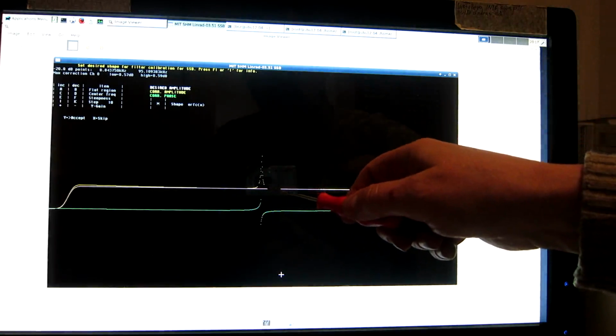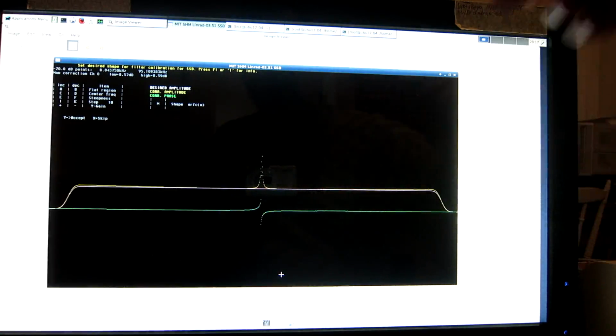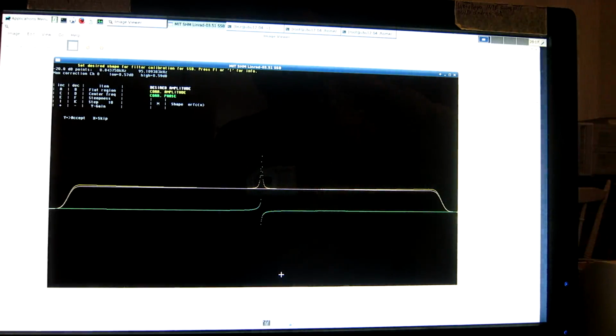But the first part of this is the high-pass filter inside the Softrock. It is not desirable to have it there, but it can probably not be removed without having problems with the blanker operation. So this is a peculiarity of the Softrock that other direct conversion receivers don't have.